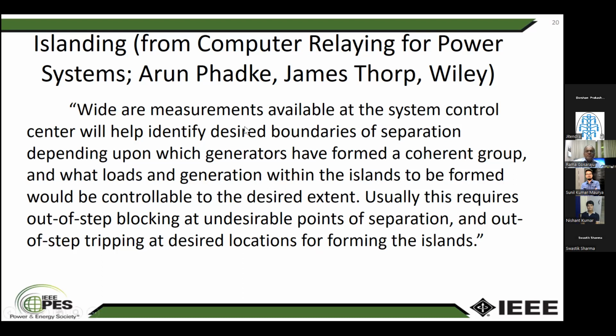So wide area measurements available at the system control center will help identify desired boundaries of separation depending on which generators have formed a coherent group, and what loads and generation within the islands to be formed would be controllable to the desired extent. So usually this requires out-of-step blocking at undesirable points of separation.